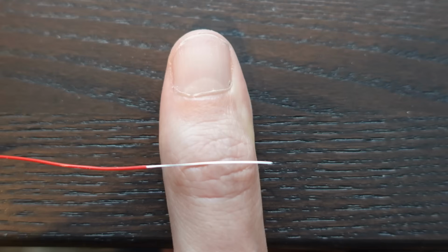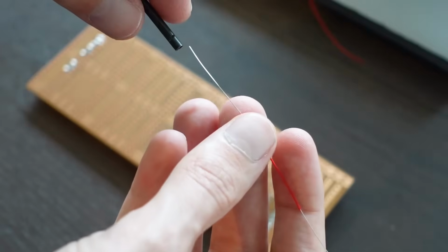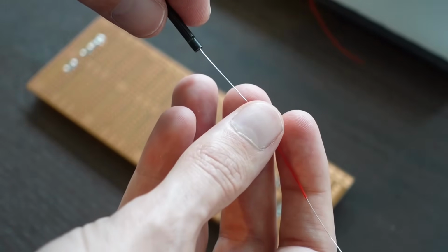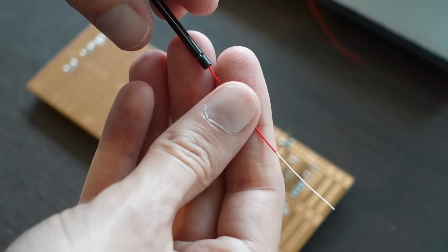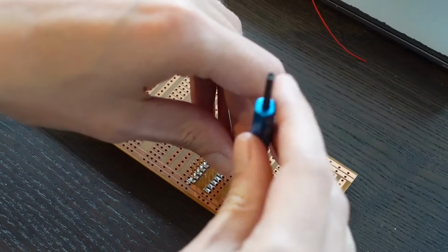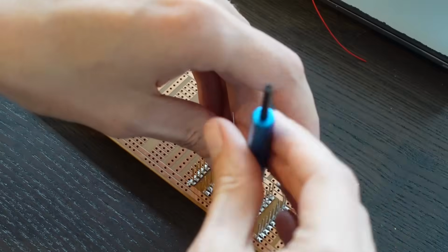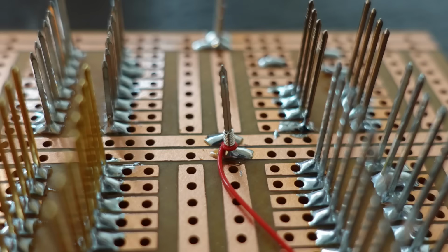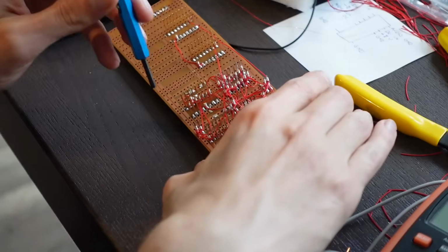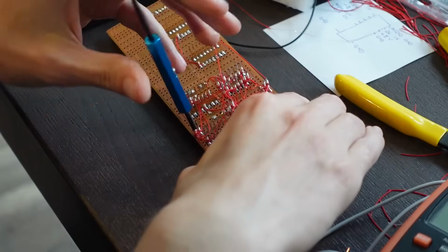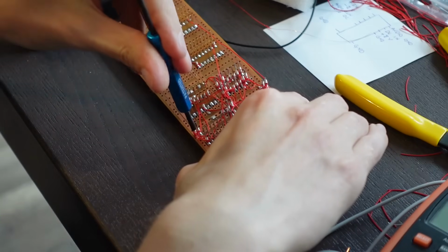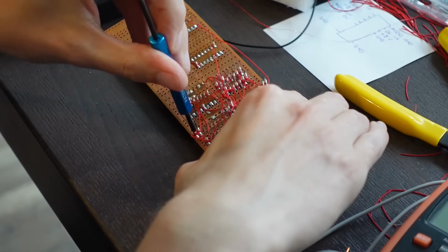You strip off an inch of insulation each end, and then load it into the tool. It has a separate hole with a slot that the wire goes into. Then you just place the tool over the post and twist. There's a notable change in resistance when it's done wrapping the wire. And there it is, a wire wrap. When you make a mistake, you just use the other end of the tool and twist it the other way. Hopefully without damaging any other wire wraps on the post.